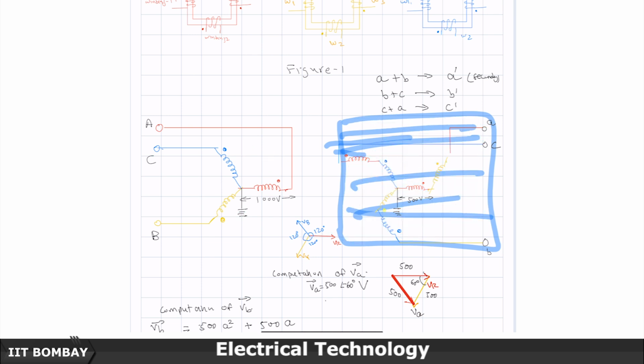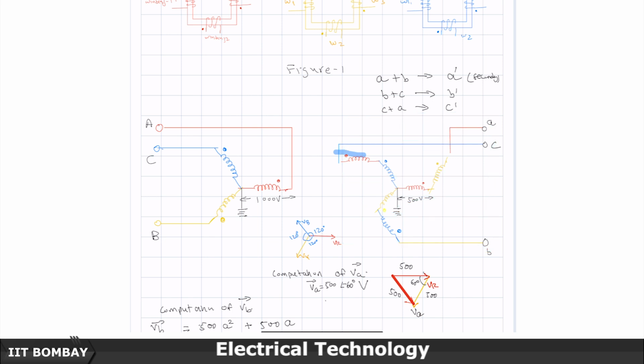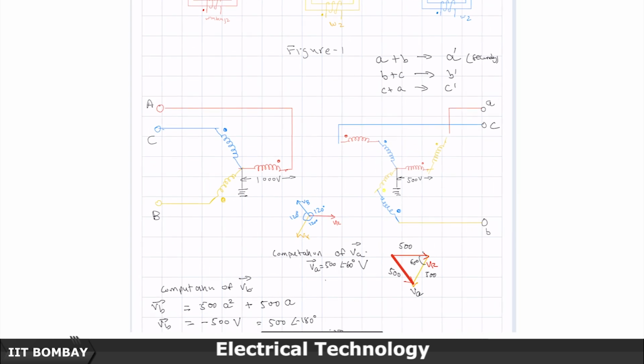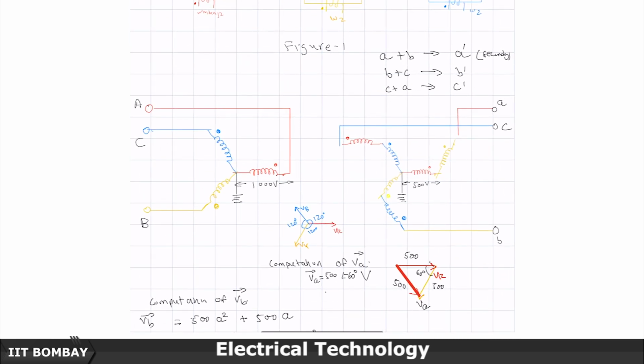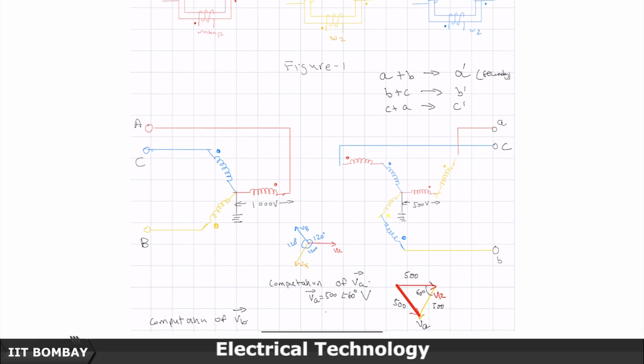what is known as a zigzag connection, to provide for specialized applications where otherwise the system is ungrounded, and we want to provide a ground, or we want to provide a path for the triplen harmonics to flow. We create this zigzag connection. Now, this is motivation, you will learn much more about it later on. This is just a motivation for you. Now, how do we interconnect the windings? So let us see why we call this Z.